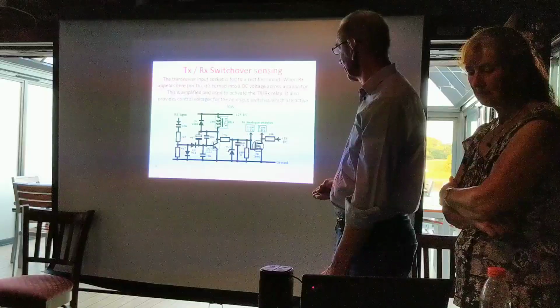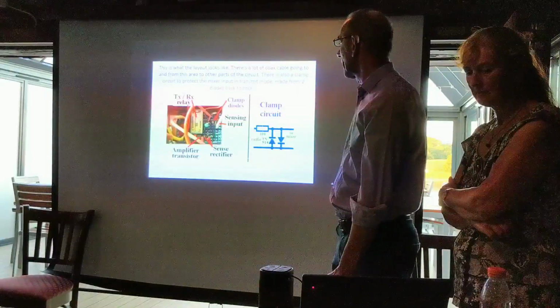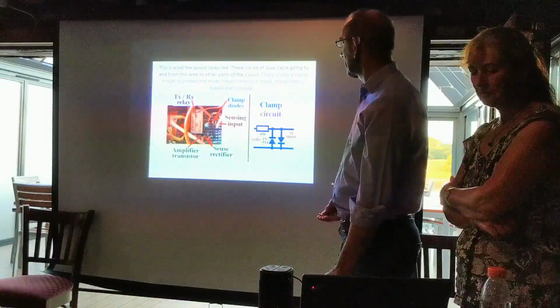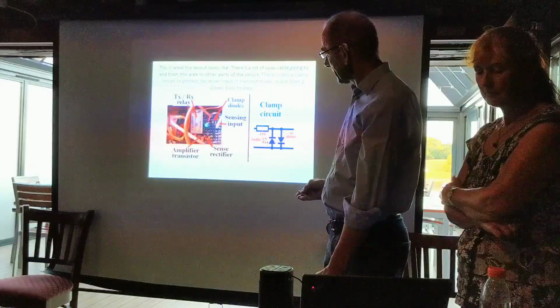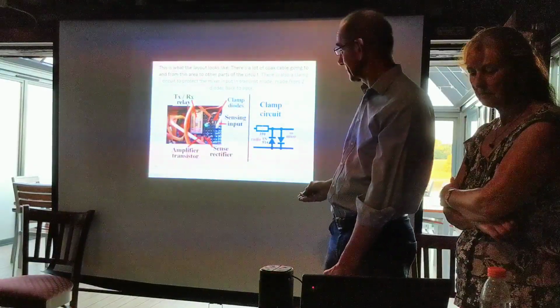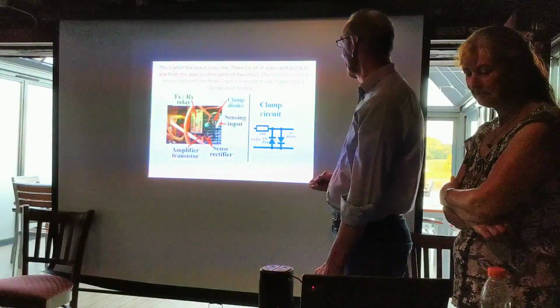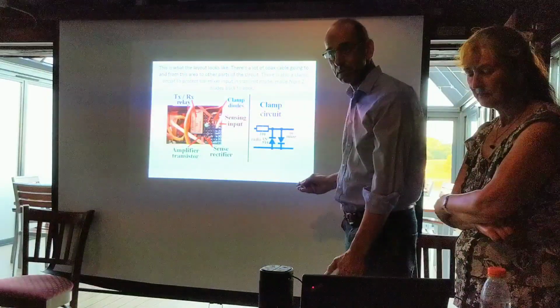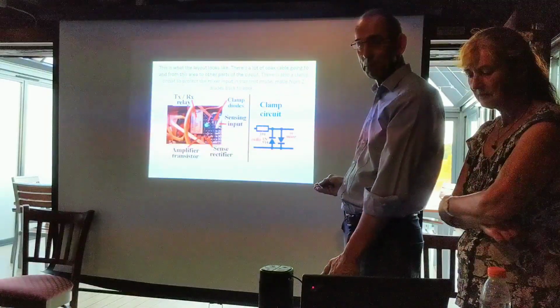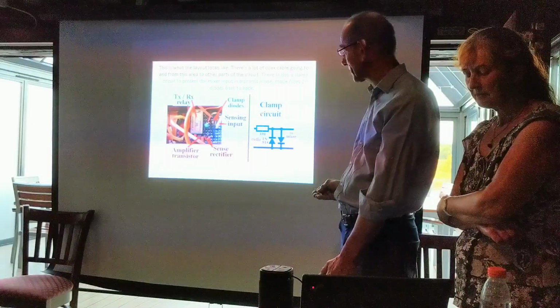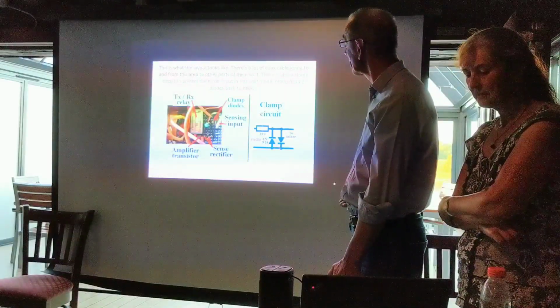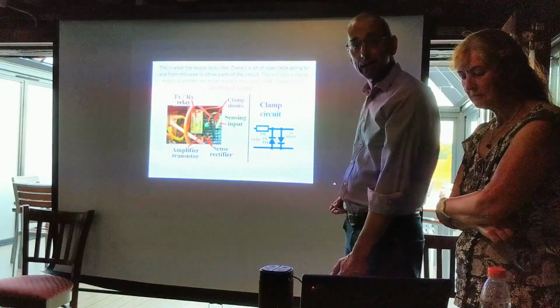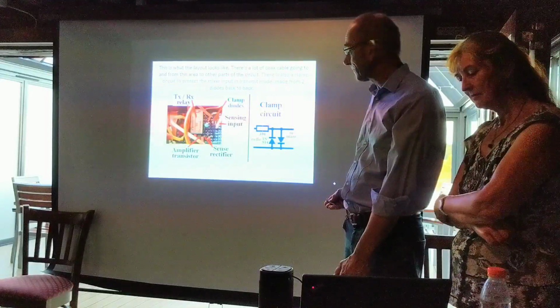Yeah, and they're actually active logic, but it's irrelevant. Right, and obviously you can see a lot of coax cables coming in and out of this bit, again, because this is where a lot of switching happens. And the clamp circuit that I talked about on the input to that mixer, so to absorb that power when you first hit the button before that switch circuit has a chance to change, that's very simply 2 diodes back to back, and that will limit the input to 0.7 of a volt.